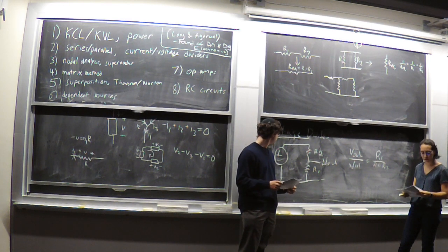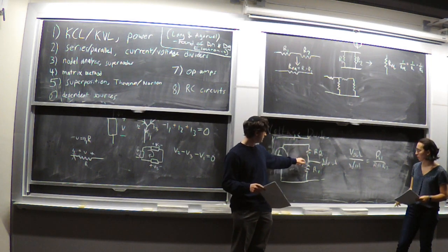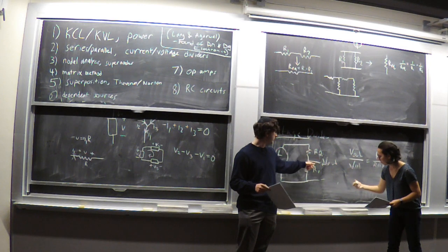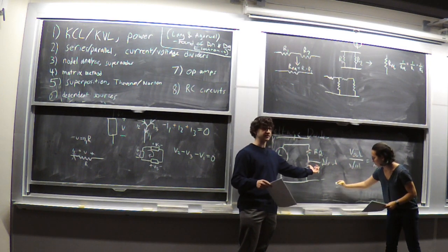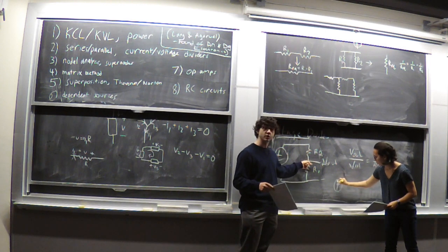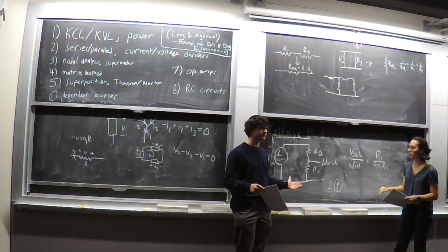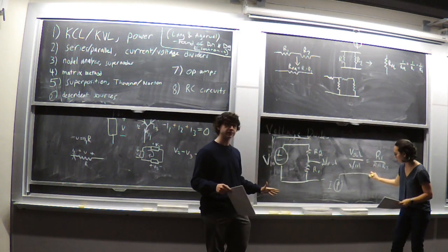I think that's the second thing to note: these two resistors are in series, even though there is this little branch here. The reason is this isn't connected to anything. This is just an open circuit, and so no current is going to flow into this little stub of a wire here. And so these resistors stay in series.